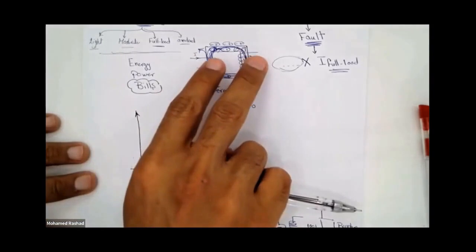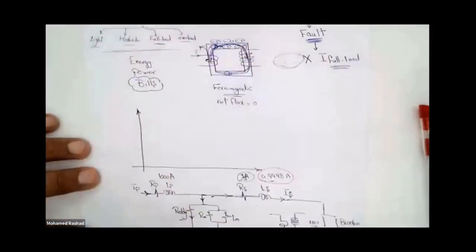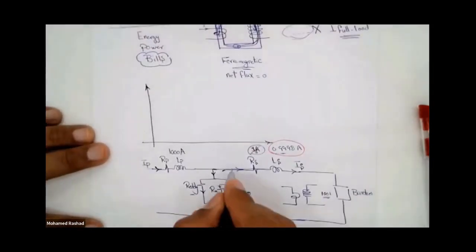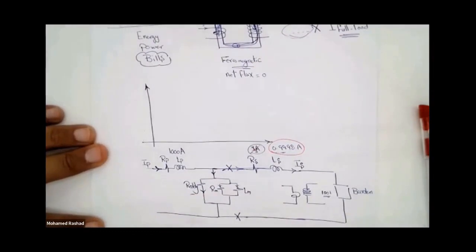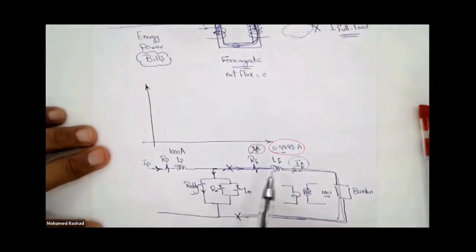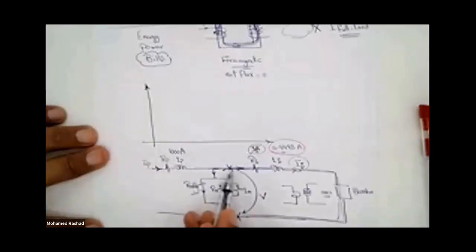This is what leads to the subtraction of the two, reaching a state known as steady state, such that a voltage appears on your secondary side, and this voltage equals the secondary current multiplied by the total resistance. I will still talk about these parts in more detail. This voltage that appears here, engineer, is what we refer to as V. The more the current increases, the more this voltage increases.